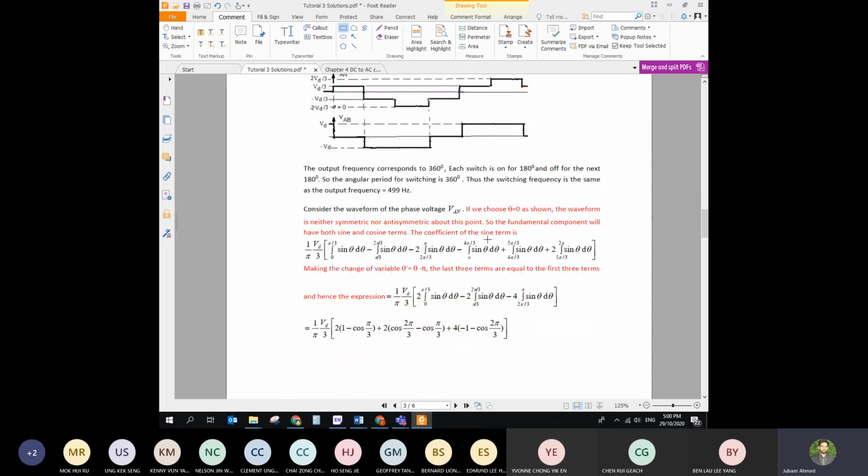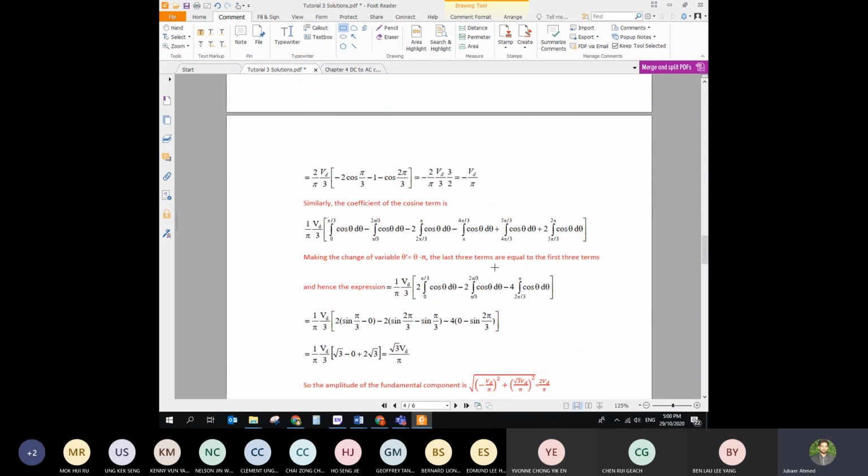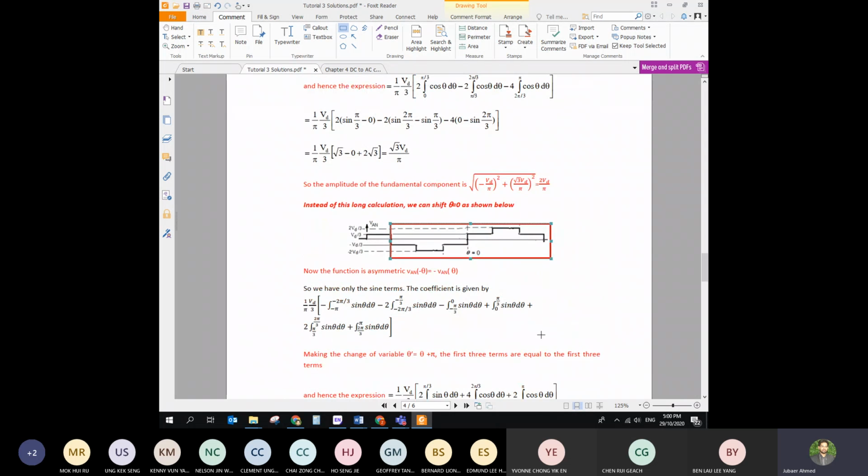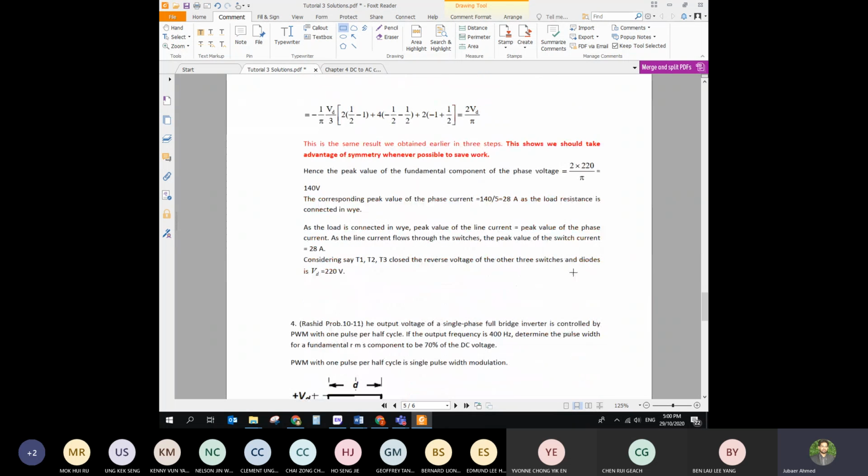If you consider it alternatingly, they are operating on the switching point. So the switching voltage is also oscillating, just like our oscillating signal on the output side. So that's why the switching voltage is exactly like VD, 220. And the switching frequency, as I told you, and the fundamental frequency are the same because this is 180 degree conduction. If it is a different conduction like 120 degree, there will be some difference between the fundamental frequency and the switching frequency. That is a discussion of a different thing.